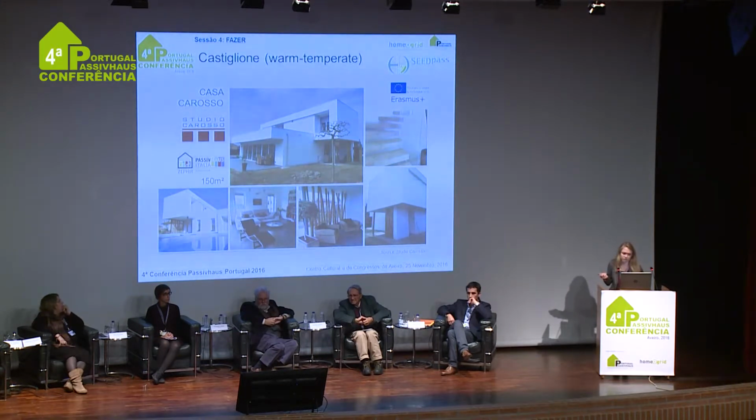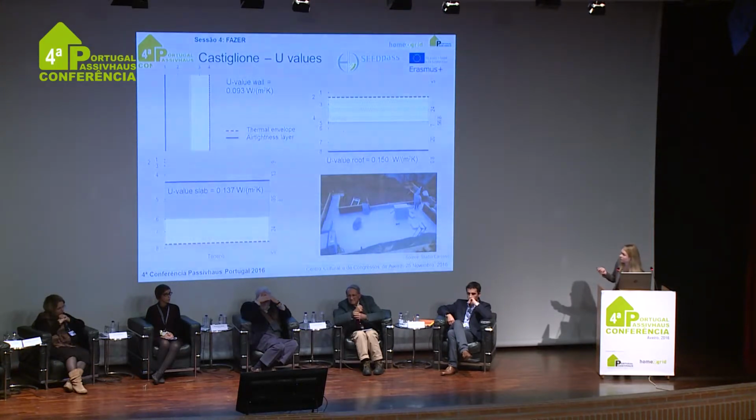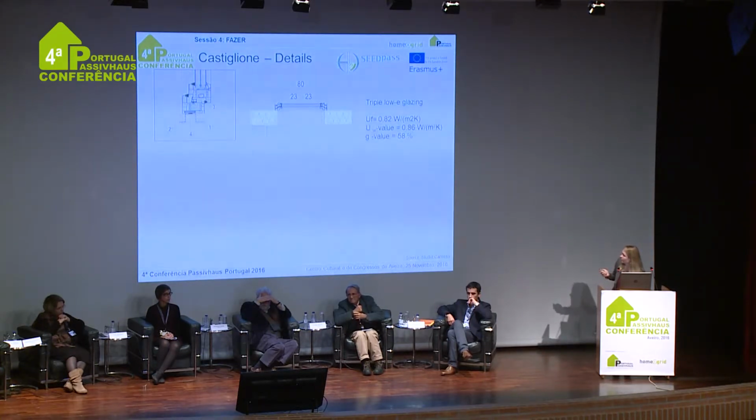It's a warm temperate climate, so a bit harsher than in most regions of Portugal. You can see that it's a modern building, but it's not very compact. That's partly why we will need very good U values, as you can see here. Regarding the windows, they have been using triple low E glazing.